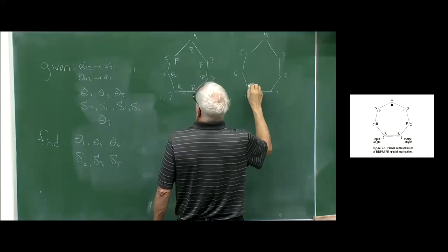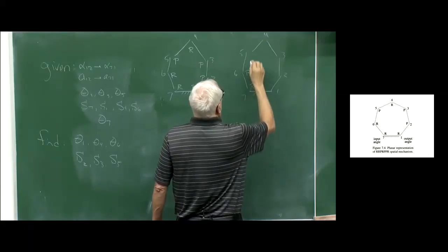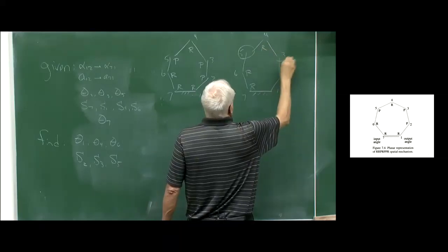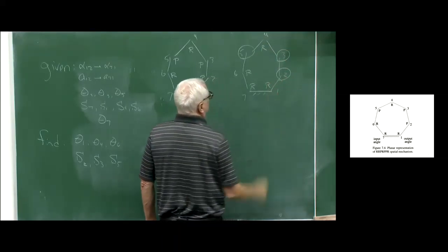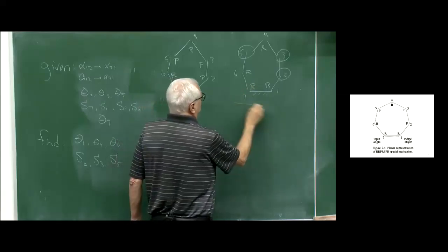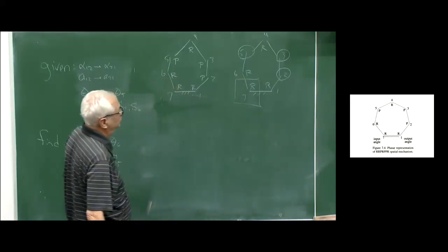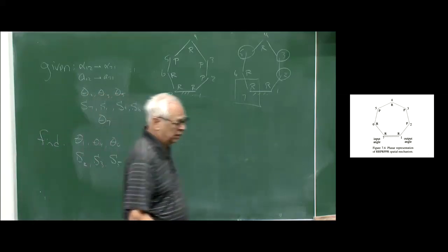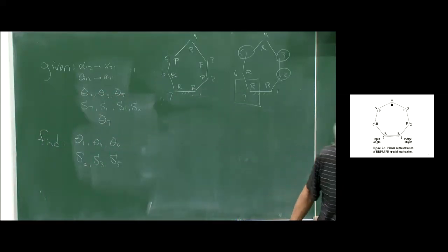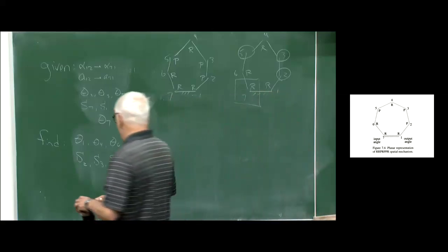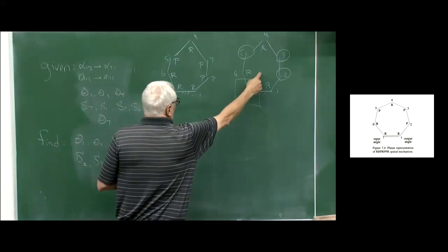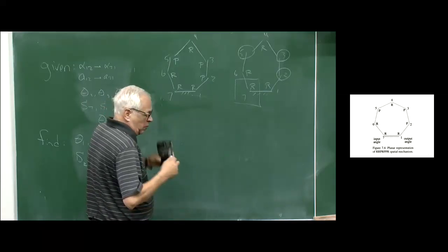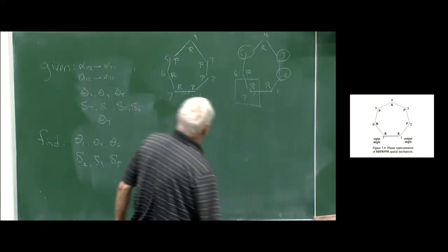Okay, revolute, there. There's a prismatic, so I know that angle, revolute. There's a prismatic, so I know those. Boom. All right, theta 7 was given. And again, in these group 1s, we have a 3D spatial mechanism that has 1 degree of freedom, whose equivalent spherical mechanism has 1 degree of freedom. We're going to be able to solve for the A and B case joint angles right off the bat. So it's just a matter of who do we want to solve for first.